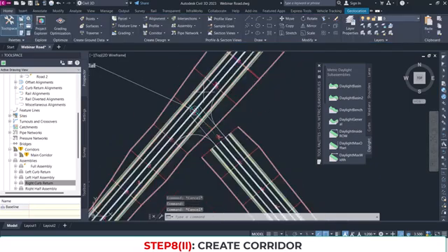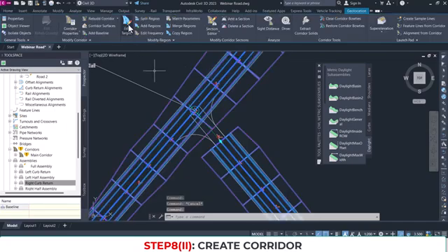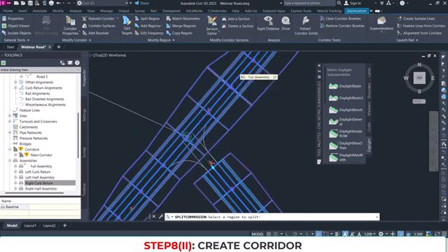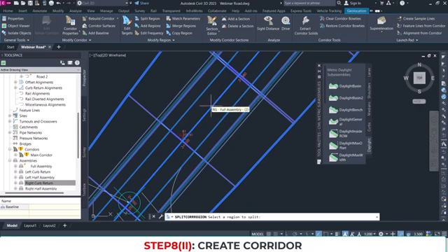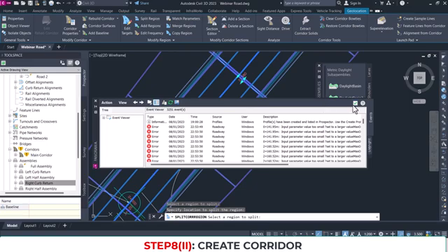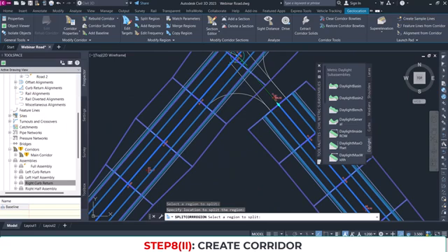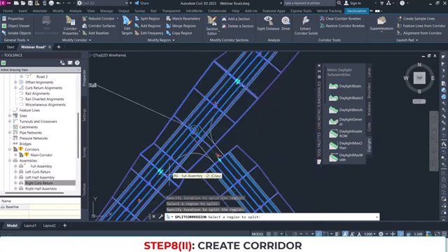So one thing is, we are going to split this corridor at this point for road 1. Okay, you have to split it. You split the region. You will see why I do that shortly. So just double click and click again anywhere here. Okay, once you do that, it has split the corridor there. It's still highlighted, so click somewhere here. Okay, and then click the corridor, click to split again. So great, if you can see, we have split the corridor at here and this point.